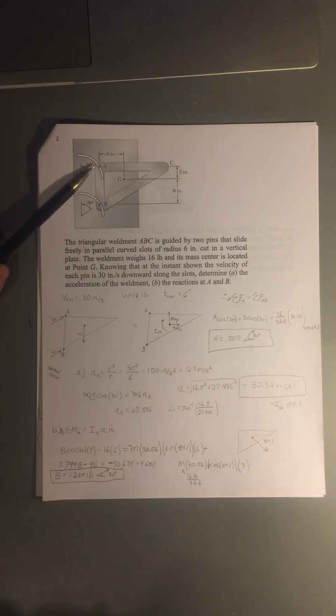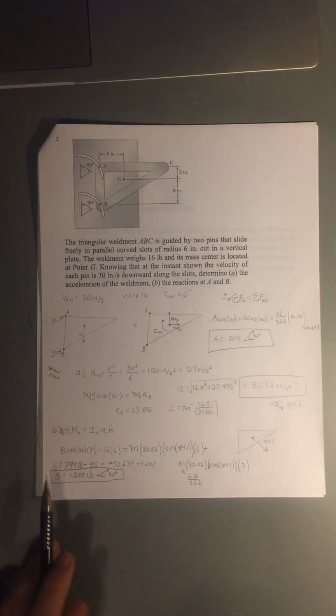And so what I decided to do first was try using a moment, because there's two unknowns here, we have the unknowns at A and B. By using a moment at A, we're able to eliminate that unknown and try and find B. And so in order to do that, we know that the moments about point A, we have the force of B, which we're trying to find, as well as the component of G. And so that's what this is here.